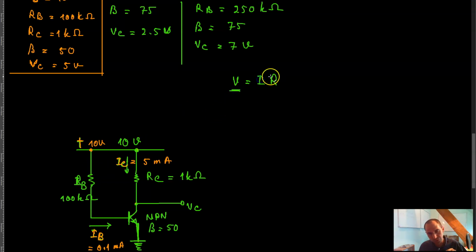Now, based on Ohm's law, by changing the value of the resistance, you can change the value of the current going through it, because if you increase your R, your I has to decrease, and if you decrease R, I has to increase, because the product of these two has to be equal to V, and V is constant here.